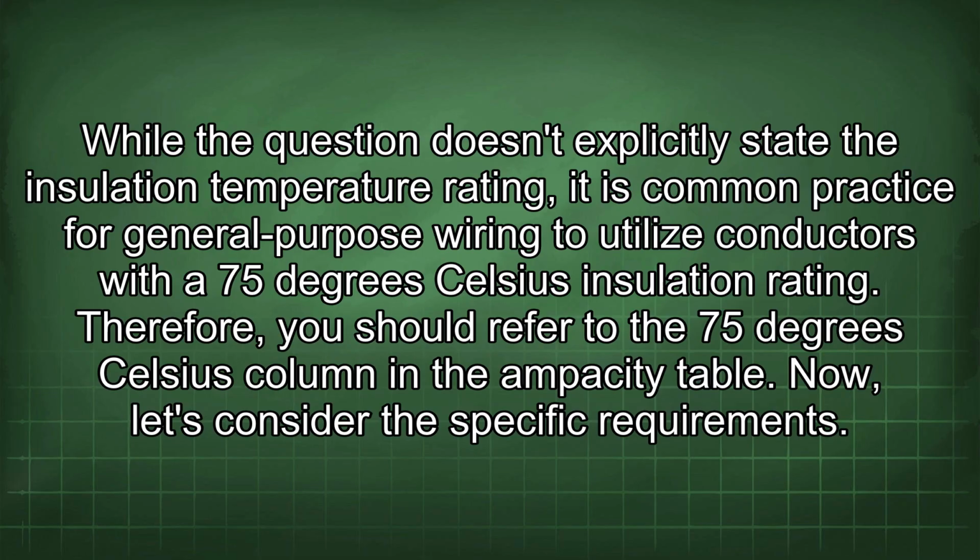While the question doesn't explicitly state the insulation temperature rating, it is common practice for general-purpose wiring to utilize conductors with a 75 degrees Celsius insulation rating. Therefore, you should refer to the 75 degrees Celsius column in the ampacity table.